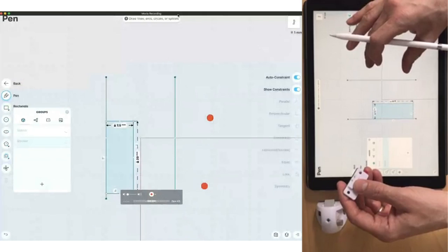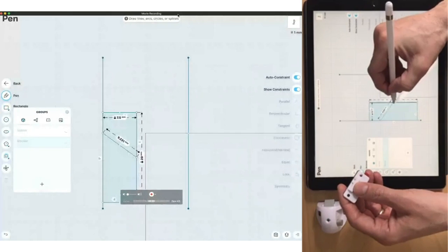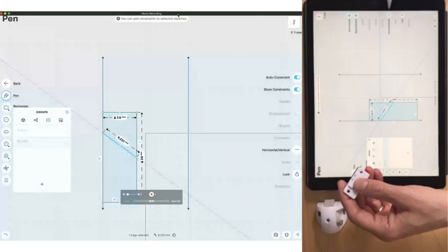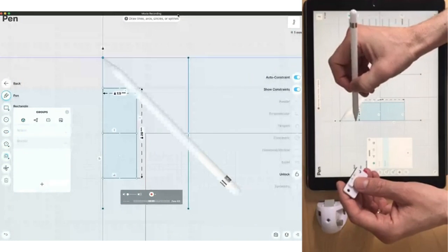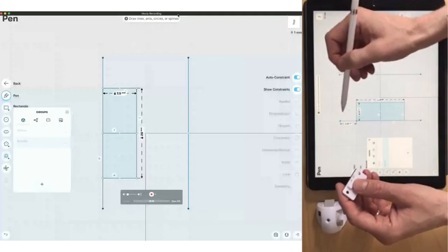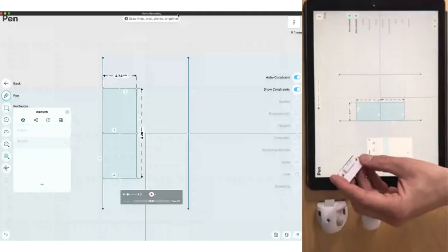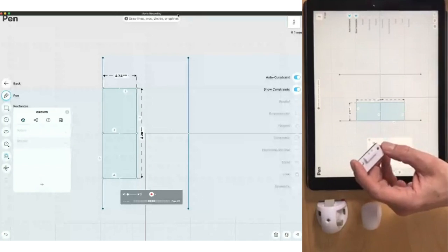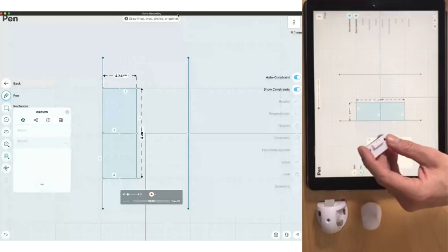Okay. Also here we would like this to be centered. We have a midpoint and midpoint, so I can simply connect a line and then do it this way instead of from here to here work with dimensions. In my sketches, I always try to put in the bare minimum because the less I have in a sketch, the easier it is to modify and understand these sketches.